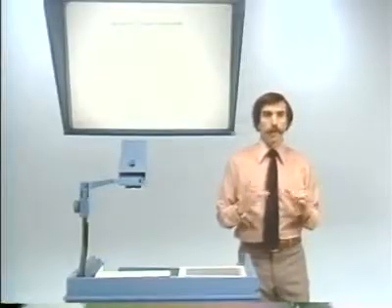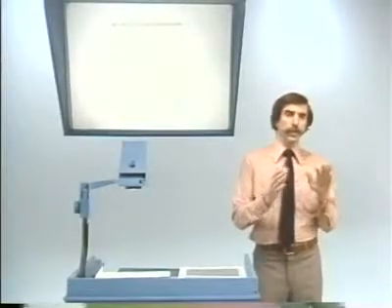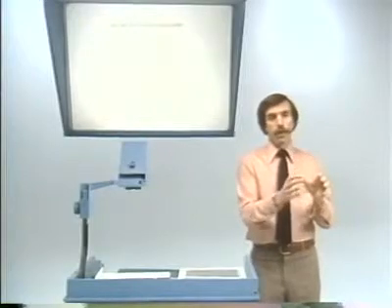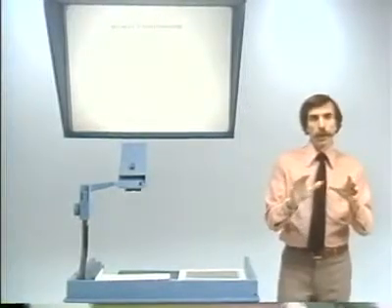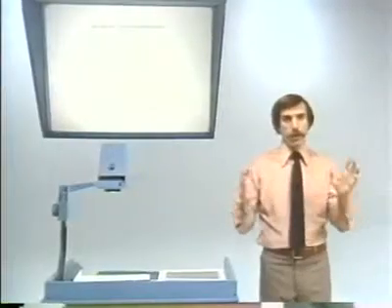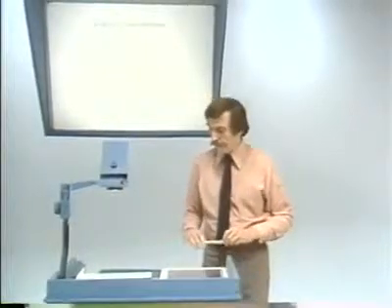And let me just say quickly and in passing that although we won't go through this, the notion of the bilinear transformation can be tied to the concept of taking the differential equation for the continuous time filter, converting it to an integral equation by integrating enough times on both sides, and then converting that to a difference equation by approximating the integrals with the trapezoidal rule. And that, in effect, will correspond to mapping the continuous time filter to a discrete time filter with the bilinear transformation. Well, we'll just focus on the properties of the mapping.